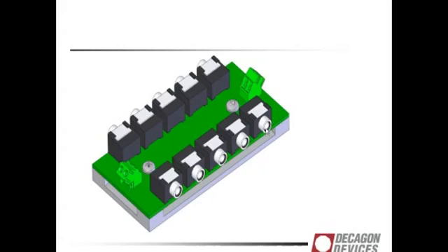You can have 10 different ones coming in. If you need to troubleshoot, you can just pop it out really quickly and plug it into your ProCheck or whatever. But I really want to just illustrate with this that there's lots of different bus designs. I've seen some that have screw terminals that are just connected by a jumper wire. I think soldering is a good way to go. Make sure you have good soldering practices, and I'll talk about troubleshooting a little bit later on.